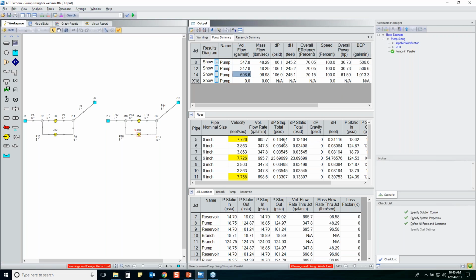695. And so the way that you can do this effectively is if your suction and discharge piping is very, very similar and your pumps are exactly the same. Same pump curve, same pump model, same lot number if possible, then that's how you can easily model pumps in parallel or series in that fashion. You want to make sure your pumps are exactly the same and not different pumps or different models, because then they could potentially fight each other, and that can cause some pretty big issues.